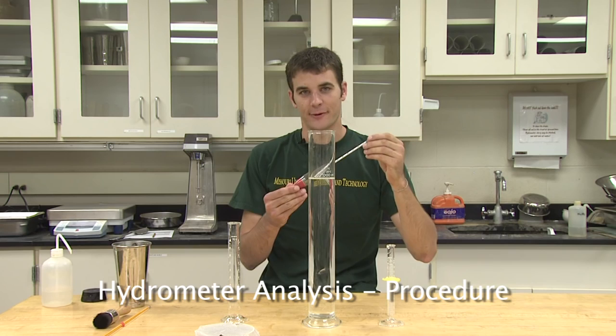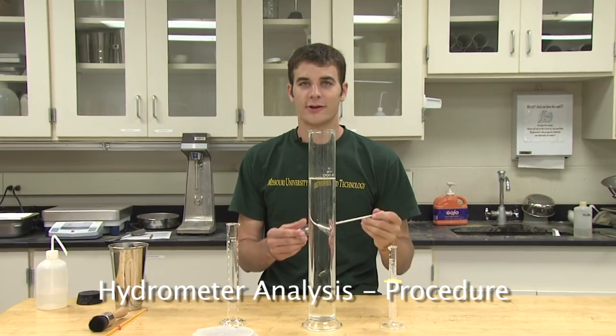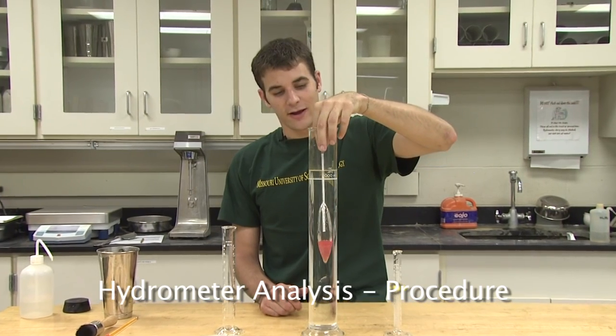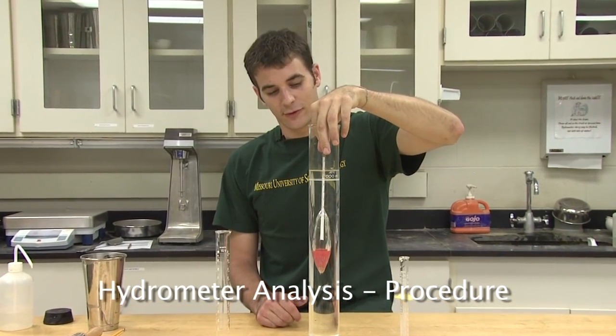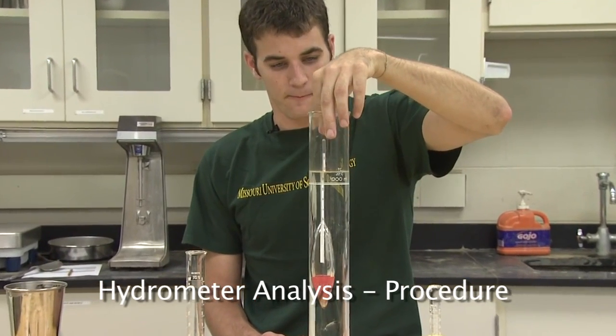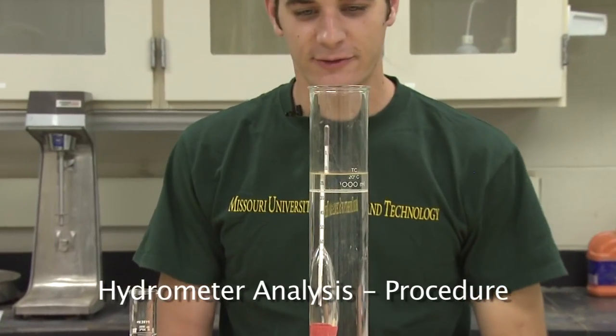While the soil is soaking for 15 minutes, you can use this time to calibrate the hydrometer. Each hydrometer is unique and will have its own unique zero correction factor. To determine the zero correction factor, lower the hydrometer into a control jar. A control jar is just a water solution with sodium hexametaphosphate, without any sort of soil in the water. The hydrometer will eventually stabilize.